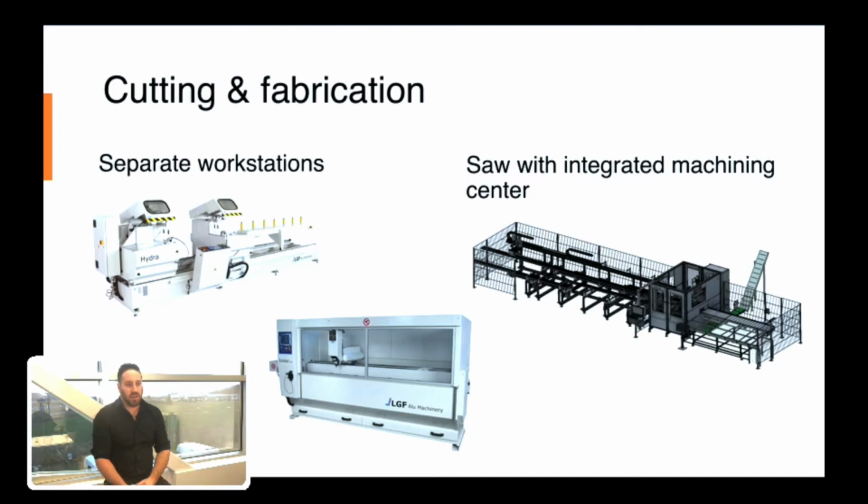In there, if you're looking at sashes, you're going to be able to do all your hardware pre-location. The only thing you're not going to be able to do would be drainage if you're looking at casement sashes, but if you're looking at hung and sliders, you're going to be able to do even your drainage as well. If you're looking at working with frames, again, everything but drainage.